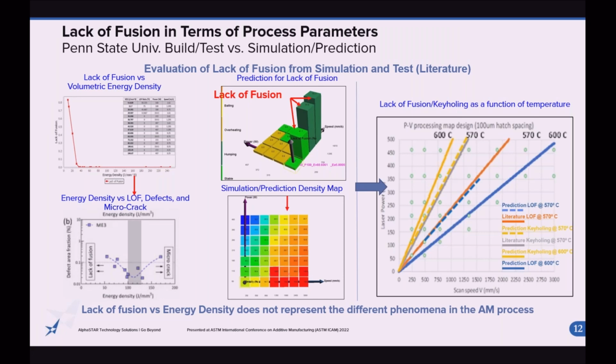But the idea being, what combination of volumetric energy compared to a percentage of defects can you use to find the sweet spot or the ideal energy density where you are not suffering from lack of fusion, but you're not accelerating the presence of defects or potential anomalies that can affect not only part net shape, distortion, warpage, but ultimately impact part performance.